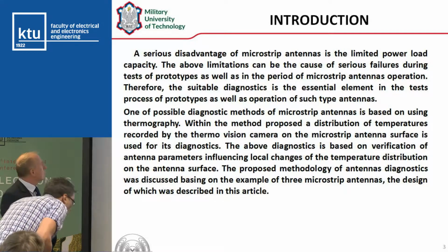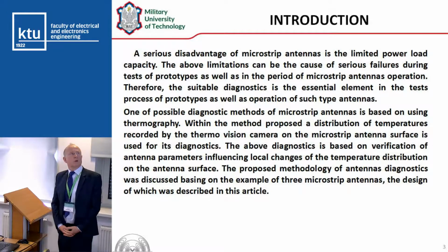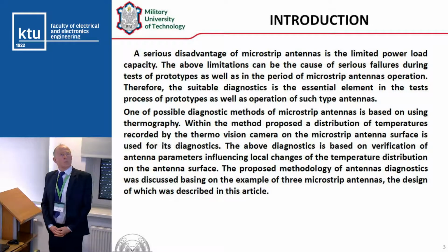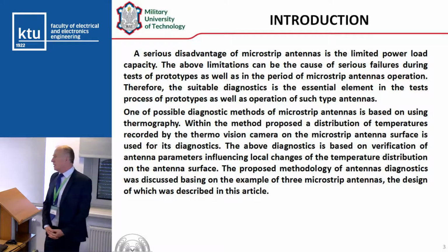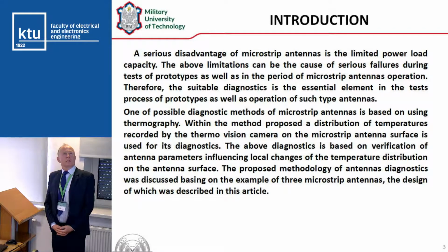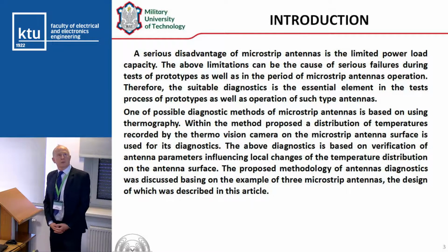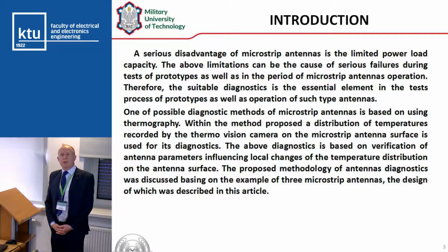The serious disadvantage of this type of antenna is limited power load capacity. Because of the small dimensions of this type of antenna, the power load is very small. This limitation can be the cause of serious failures during the test of antenna prototypes as well as in the period of microstrip antenna operation. Therefore, diagnostics is an essential element in the test process of prototypes as well as in the operation of such antennas. One possible diagnostic method of microstrip antennas is based on using thermography.